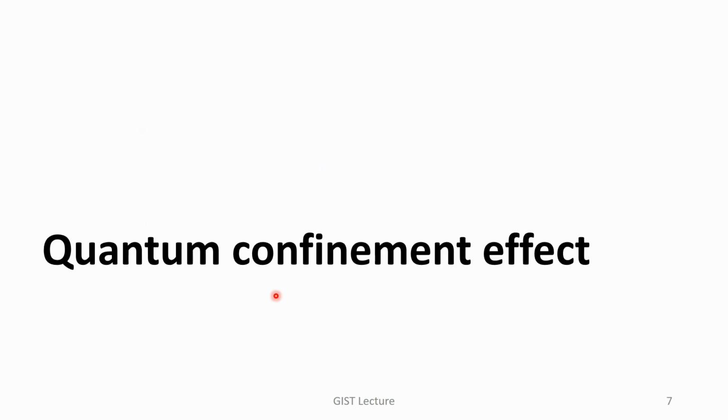Now, we are coming back to our main discussion. In the MOSFET, we have the quasi two-dimensional electron gas. Electronic motion along the vertical direction is prevented by the potential barrier. The electron confined within a short range has discrete energy levels.